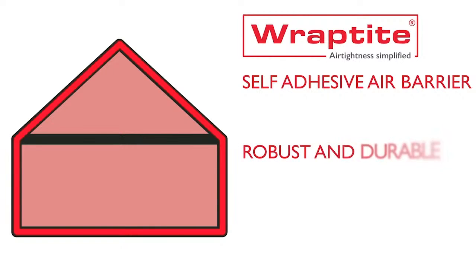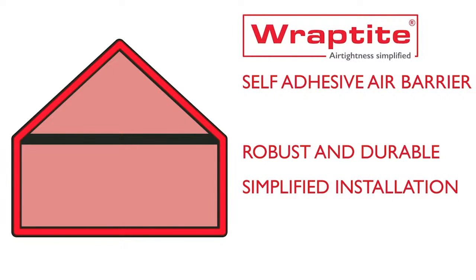Being fully self-adhesive, the material also bonds to the substrate, reducing the likelihood of damage from extreme weather conditions during construction. It also makes for a simplified installation process compared to mechanically fixed external membrane. It also reduces the sealing requirements around internal surfaces.